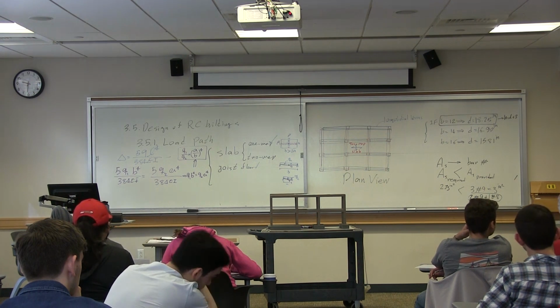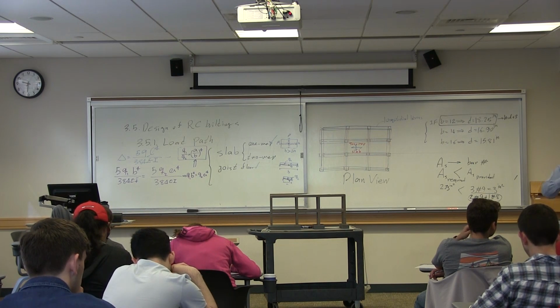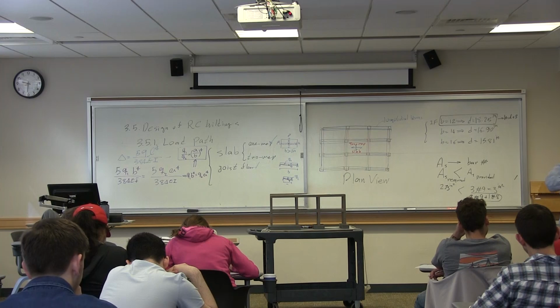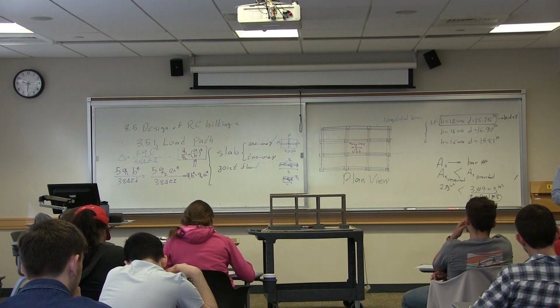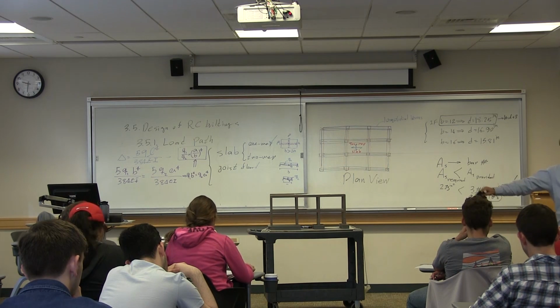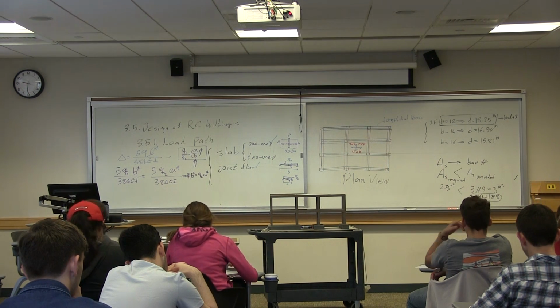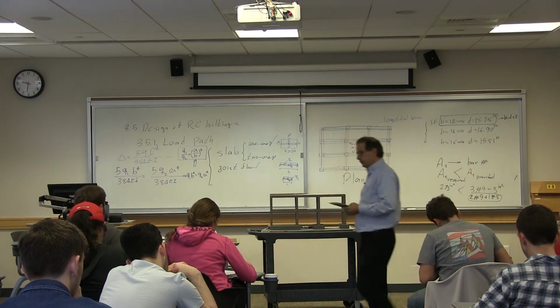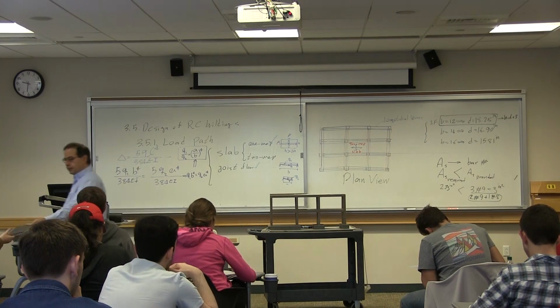The longer one. So this beam and this beam need to deflect the same amount. Which one is going to see more load to deflect the same amount? In other words, I have the 5 foot long wood and the 10 foot, so therefore more load goes in the shorter direction. Thanks.